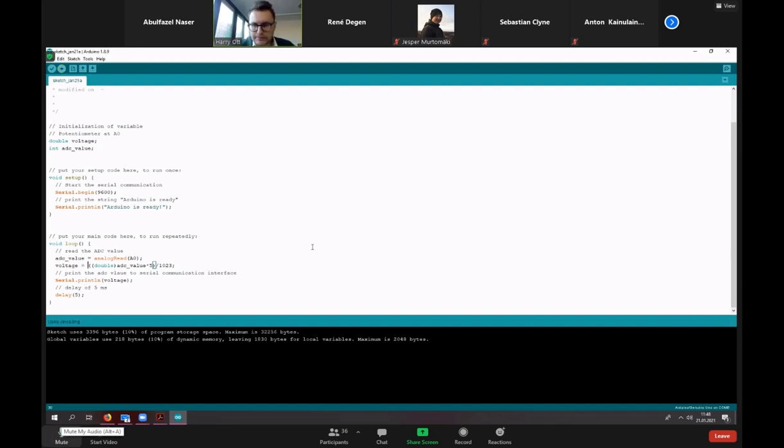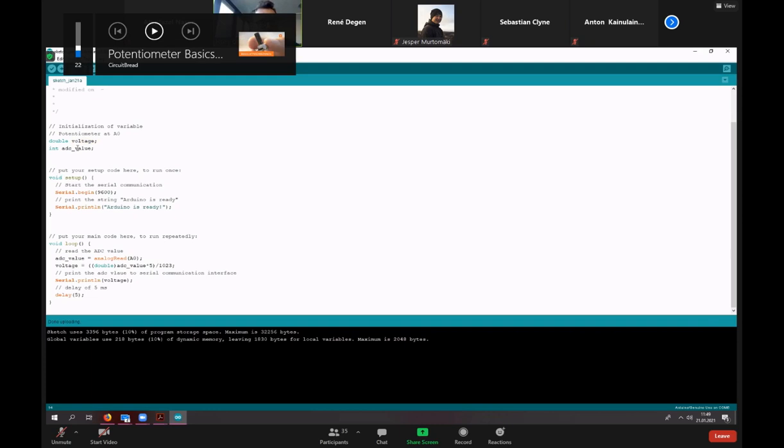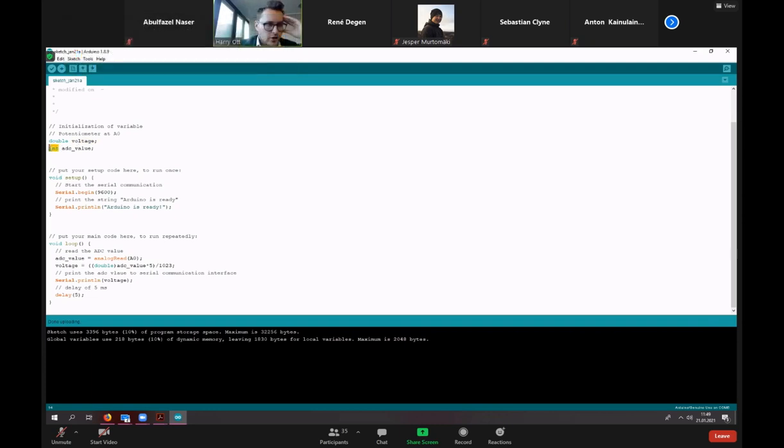Could you explain what double did again? What it means? I didn't get it. The typecast here. Yeah, just double. What does it do? That's our data type. So when you are programming, you define or allocate variables. We have decided before what kind of data type it is. So the ADC value can only be an integer value. Therefore, we define it as an integer.